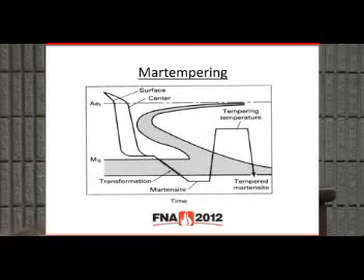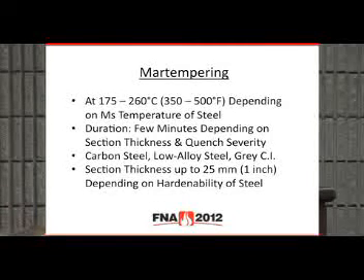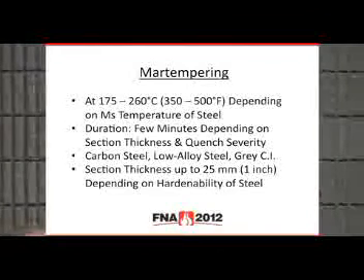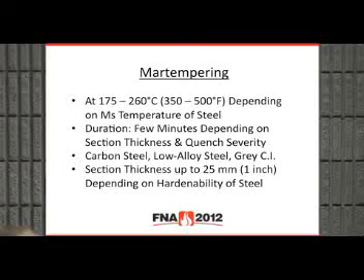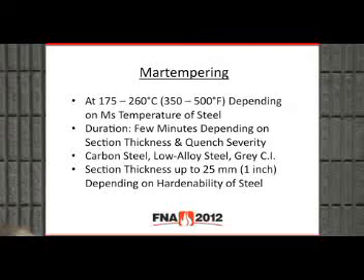Let's look at the process called martempering. This is the same slide we talked about earlier. The quenching is interrupted at a temperature slightly above the MS temperature, and then the components are allowed to air cool or water cool, and then you naturally carry out the tempering process.